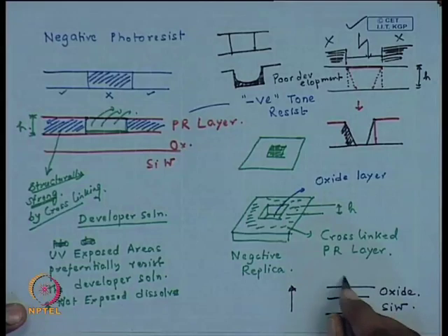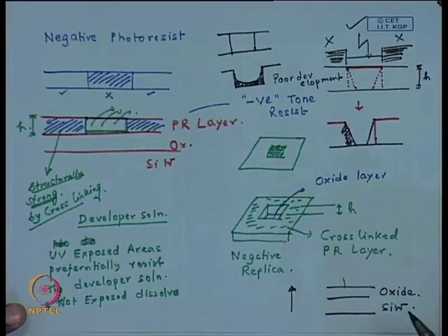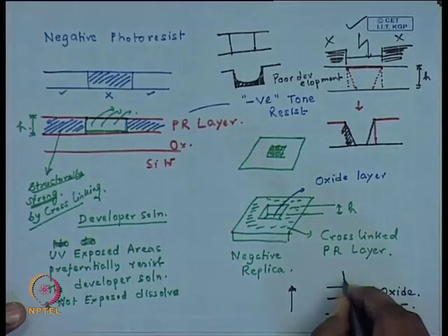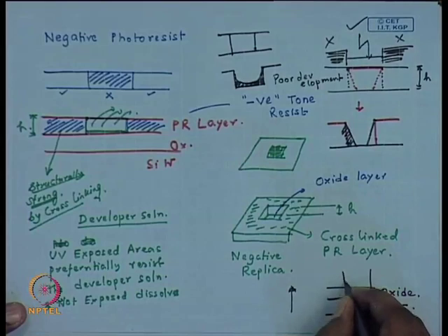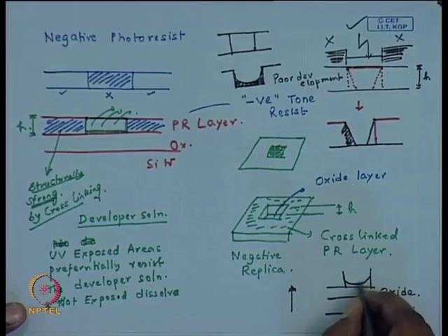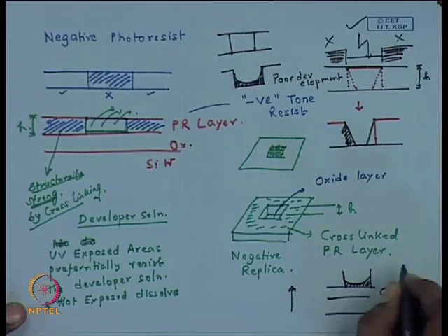So, your final objective is to also get rid of the oxide layer, so that you have access to the silicon wafer where you can have your doping reaction. But if on top of the oxide layer the photoresist layer is not fully developed, not properly developed, and a remnant layer of underexposed or overexposed or unexposed photoresist remains, that is going to spoil your entire process.